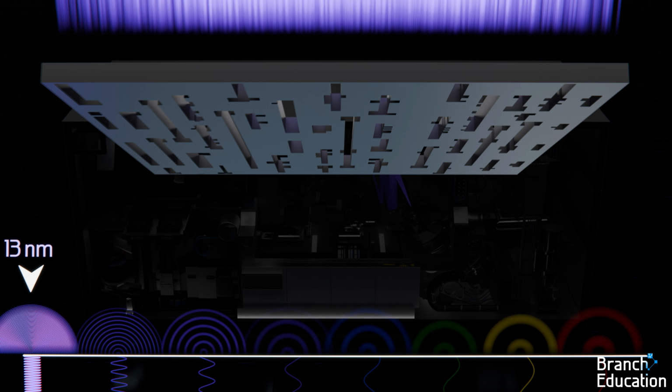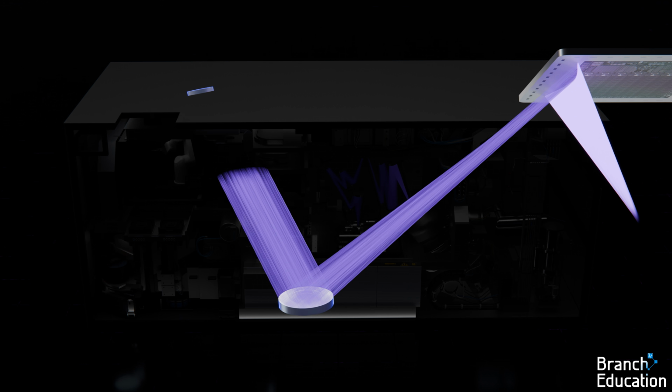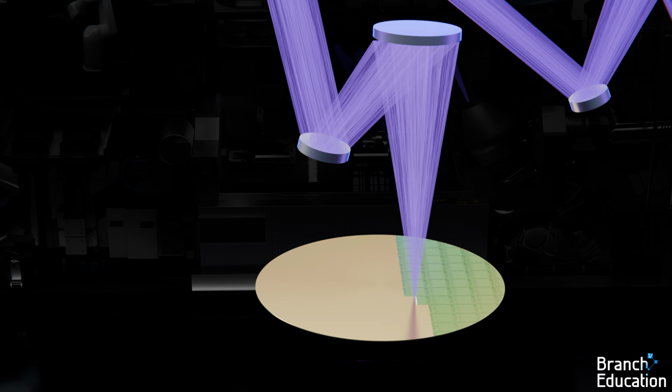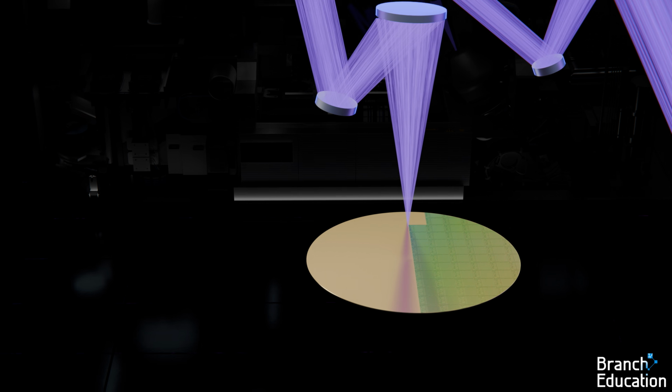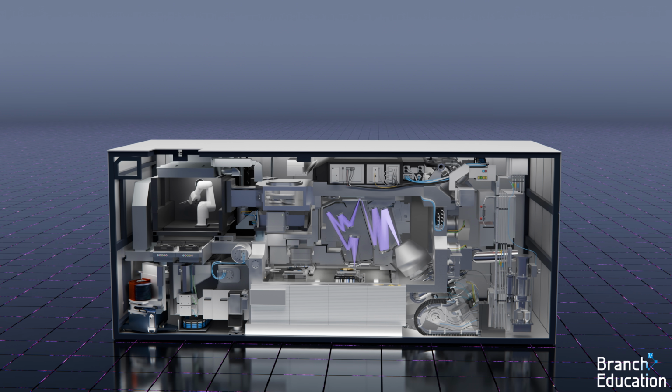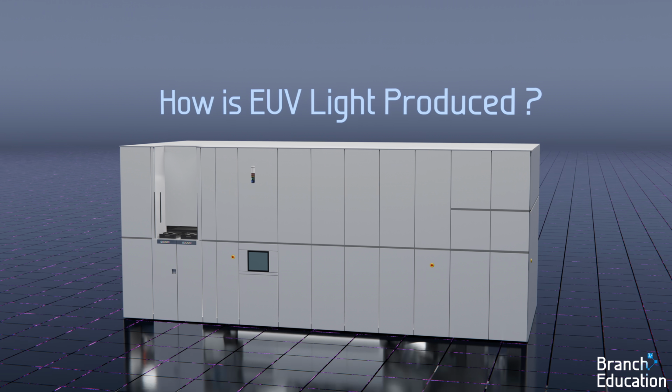As the EUV light hits the pattern, the light passes through and the pattern of the photomask is imprinted into the light, and the light diffracts similar to the double slit experiment. This imprinted light then passes into the projection optics mirrored lenses, which are used to focus and scale down the pattern and project it onto the wafer. So now that we understand the need for EUV light, the next question is, how do we produce it?